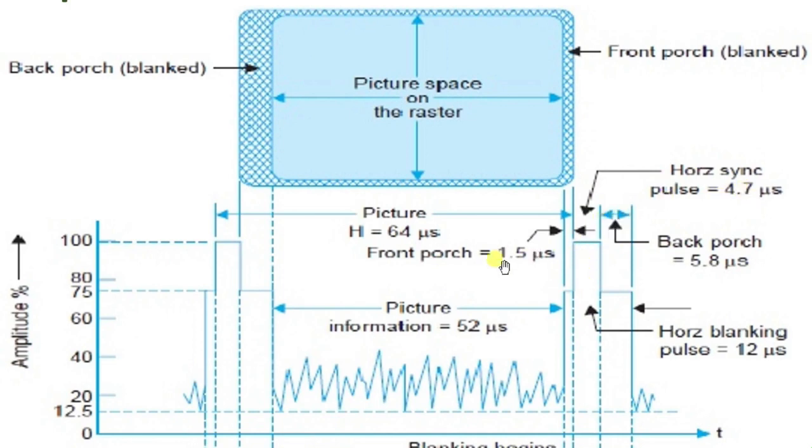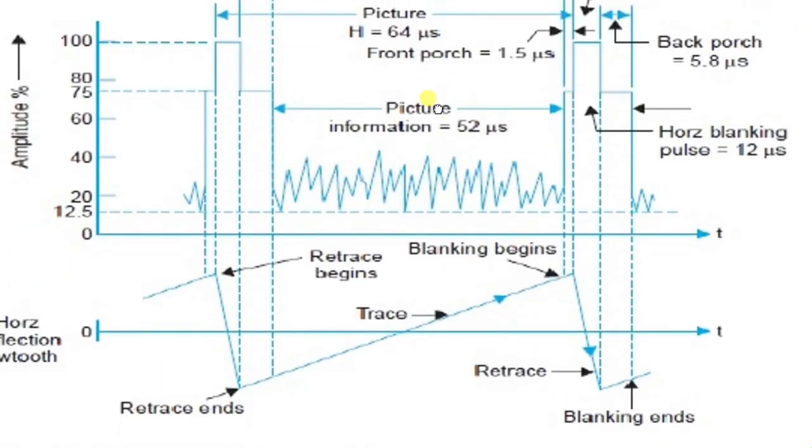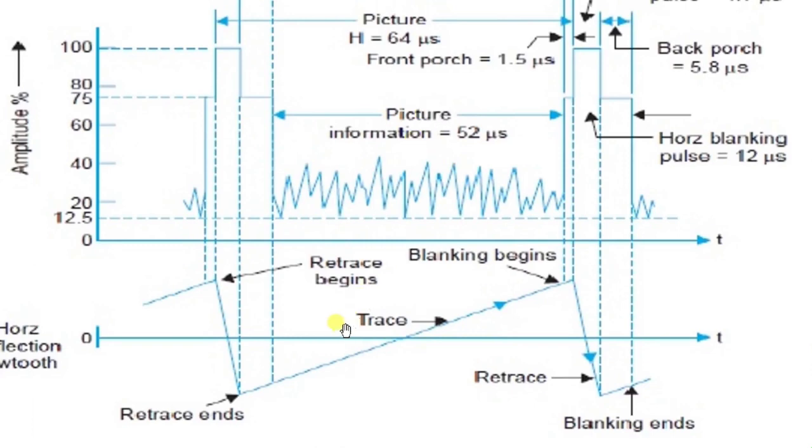Figure 7.6b shows the effect on the picture tube screen of the front and rear porches during horizontal blanking. The brightness was set higher than normal, to make the blanking brighter than black. Also, the horizontal scan phase must be shifted to include the blanking time in the tracking time.